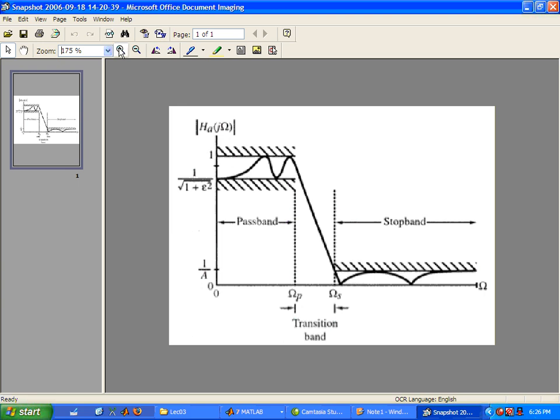So going purely for intuition now, I was going down the list and I was asking you, all right, so let's start with the stop band frequency. So let's start with this picture, and let's say that in order to build a filter that satisfies everything here, I need to have a filter of order n. So it could be, let's say, a fifth order filter, whatever. So now I want to increase my stop band. So let's say now I'm going to keep everything the same, but I just want to increase the frequency of the stop band. So increase it. So is that going to require a filter of a greater or a smaller order?